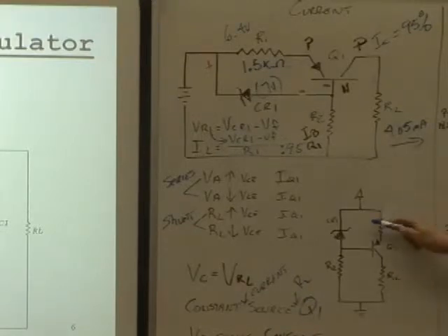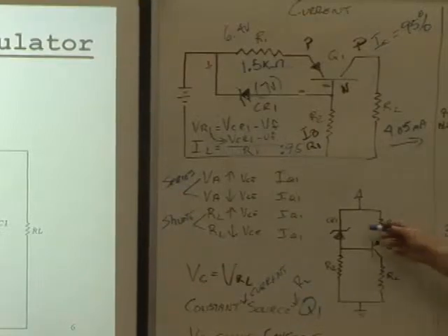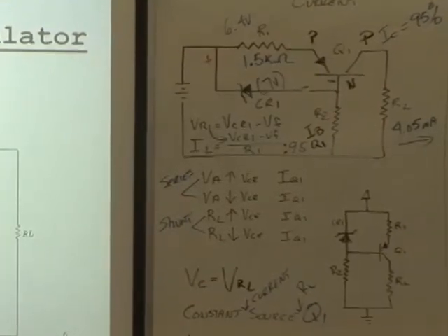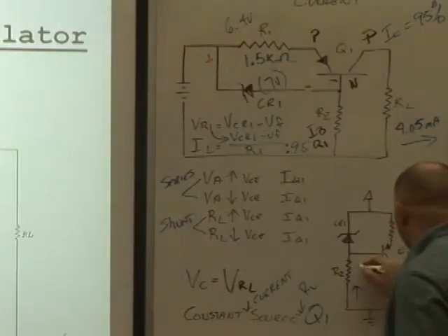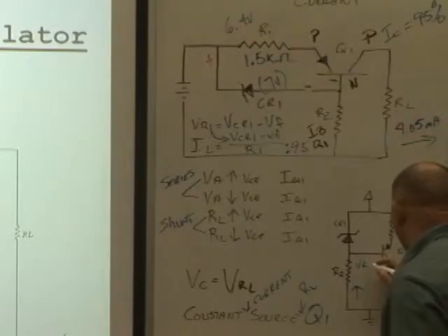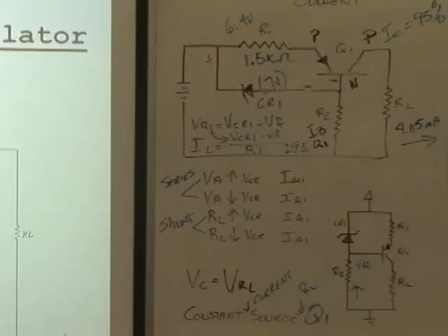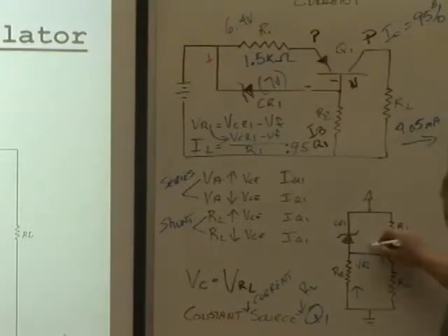Look here, this top part is pretty much locked in, isn't it? Yes, sir. Because I've got the Zener and I've got R1. R1's voltage drop isn't going to change much, is it? Yes, sir. So basically, you're dealing with the bottom half of the circuit. So if I have an increase in current, is VR2 and the base voltage the same thing? Yes, sir. So if there's an increase in VR2 due to an increase in overall current in the circuit, I have what type of transistor?